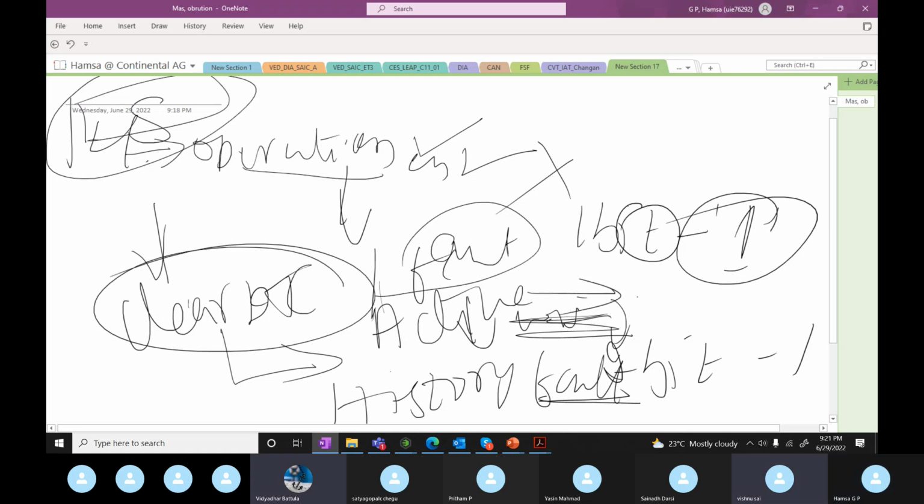Active fault means a fault present in the present duty cycle. Sorry, can you please come again? Active fault means it is confirmed in the present duty cycle or operation cycle. History fault means the problem occurred in the previous operation cycle, but presently it is not there.